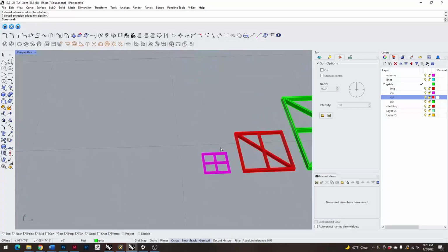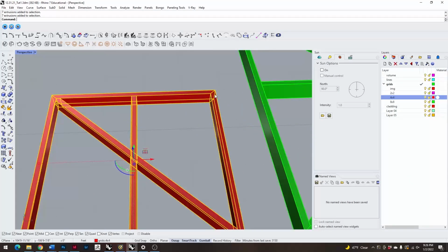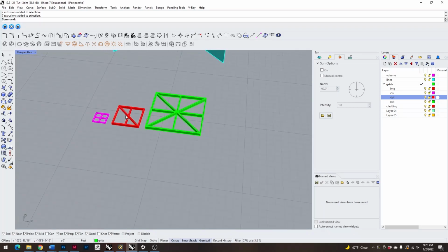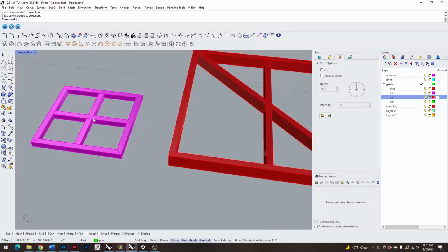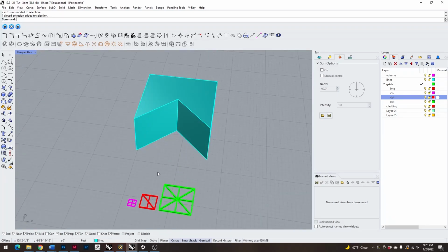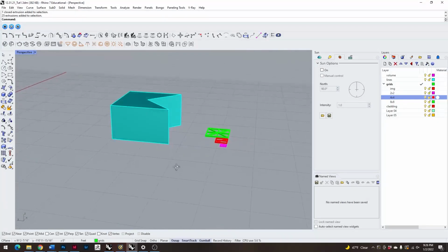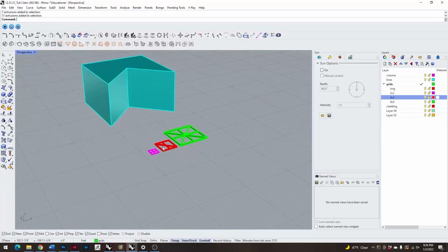And bear in mind that if you do that properly, such that these are all linear closed extrusions, it will save you tons and tons of time at the back end when you're making your drawings. So I really do encourage that you keep that in mind and you, at this point, have everything modeled very cleanly. So the next step is to take your volume and these linear closed extrusions, grouped accordingly based on 2 foot, 4 foot, and 8 foot by 8 foot grids.